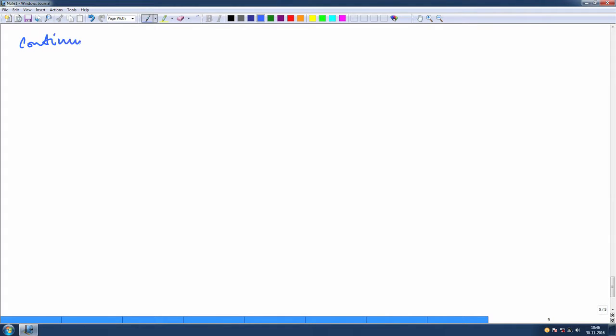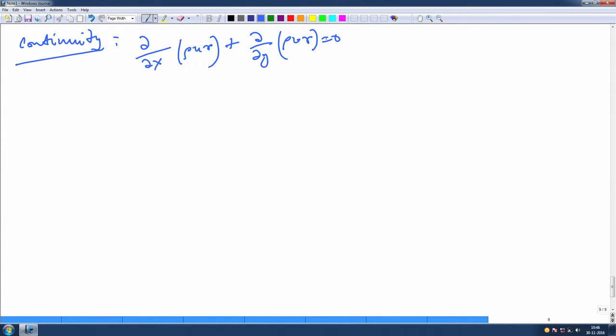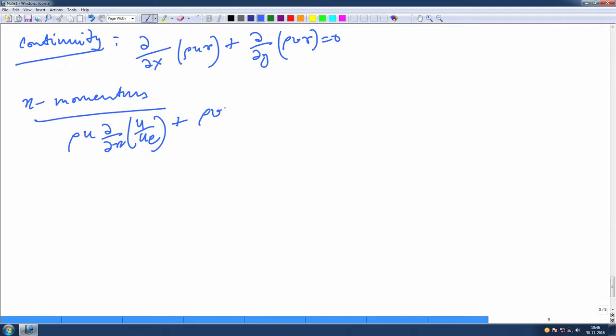So, continuity. The good part is that we do not have to solve all of them. We are not going to work out the math like that, but we are just going to pose the problem, and we have already explained how the problem can be solved. So, it requires that Falkner-Skan type of solution. That is the continuity equation, the x momentum equation, and you will find a lot of similarity with your flat plate boundary layer. We will say what UE is, just hold on for a second till we establish these equations.